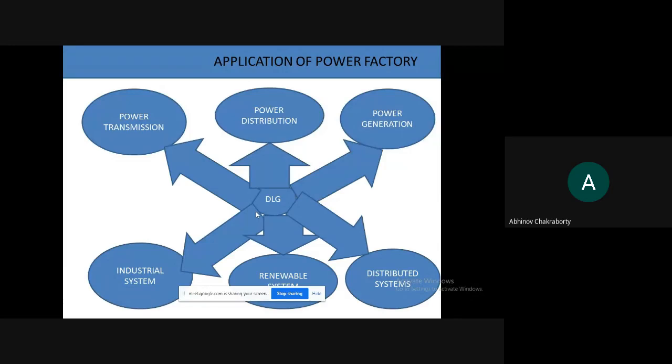And in your industries, again, you have a very vast distribution of the feeders. Why? Because you have a classification of the feeders. Somewhere you will have your PCC type of installations. You will have your MCC panels. You will have your APFCR panels. Right? So these different types of panels have to be given with different arrangements, with different feeders, with different power requirements, with different production units. The ratings have to be different. The contactors that have been used on those panels have to be different.